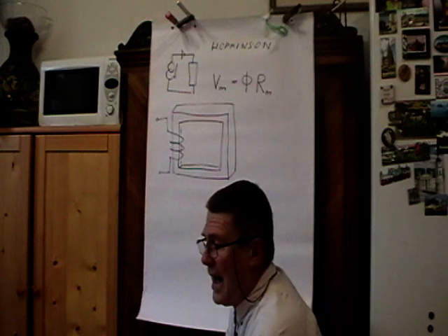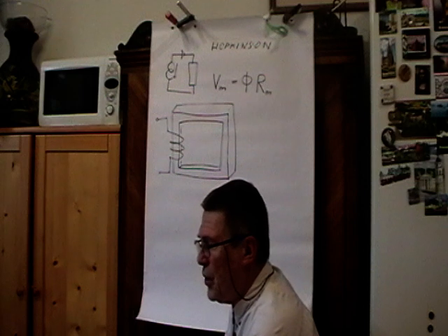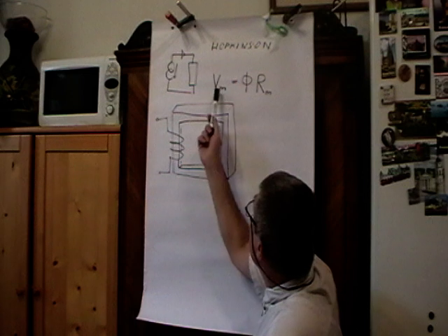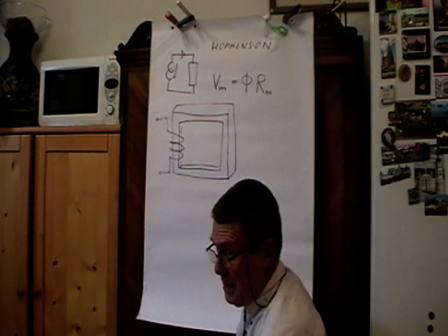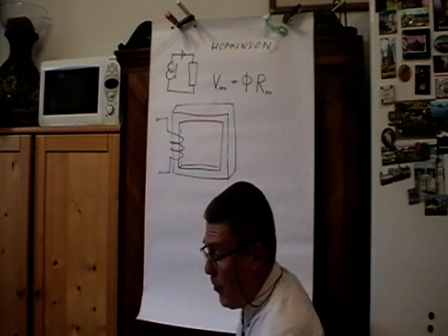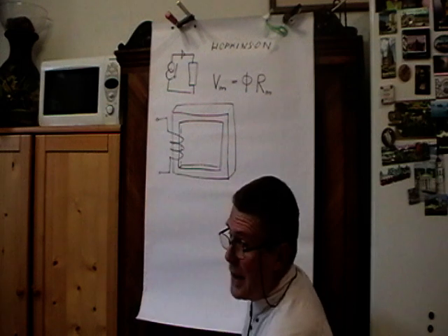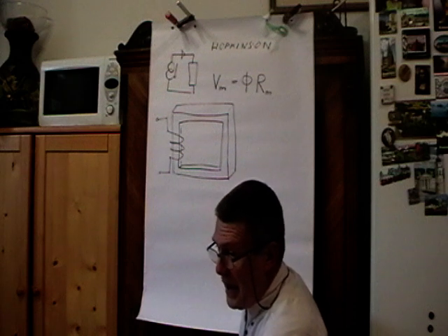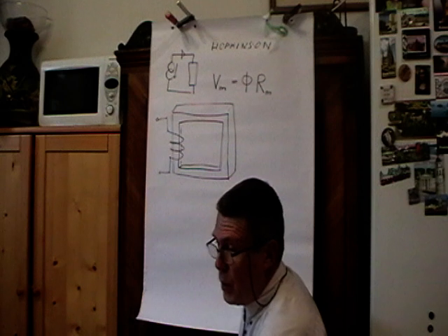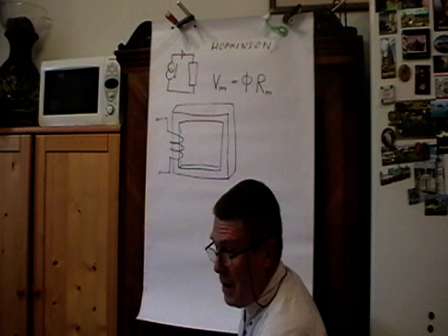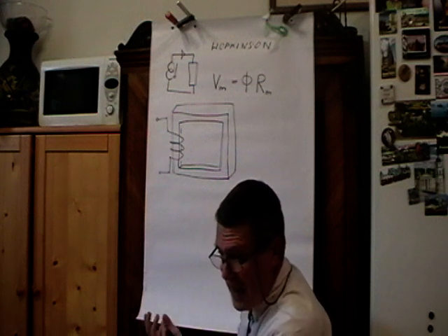But any electrical engineer should think that there is a second component in determining this magnetomotive force, and that is the number of turns. You could get the same effect by putting there one turn and 1 kiloampere, or 2 turns and 500 amperes, or 1000 turns and 1 ampere, and vice versa.